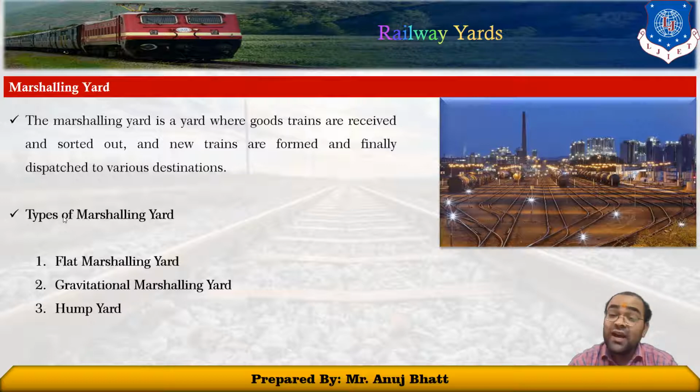A marshalling yard should be so designed that there is a minimum detention of wagons in the yard, so that sorting can be done as quickly as possible. These yards should be provided with the necessary facilities such as a long shunting neck, a properly designed hump, and the braking arrangement in the shape of mechanical retarders. And all these depend upon the volume of the traffic.